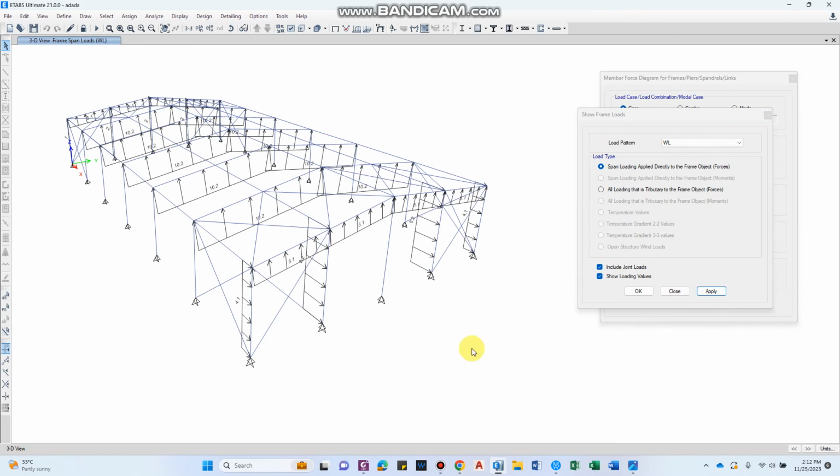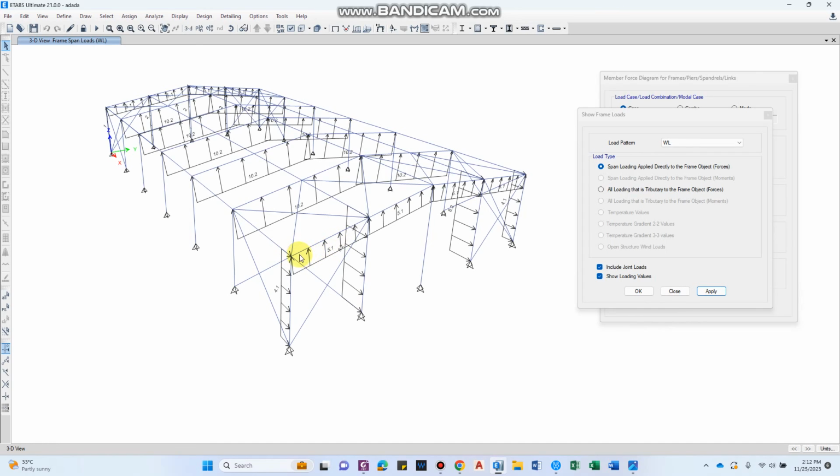If the wind is blowing from this direction, because the bracing comes into play when the wind is blowing from this direction, with the distance from the first portal frame, the wind load coefficient at the roof decreases. For example, the wind coefficient at the start will be maybe minus 0.9, and then at the mid span the wind coefficient reduces to minus 0.5.